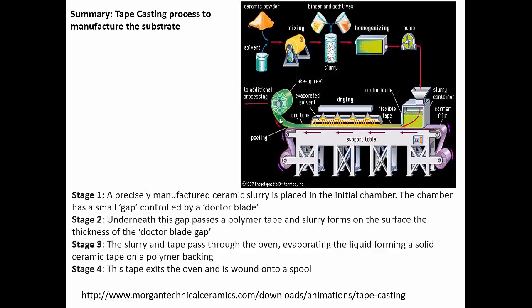So this is scalable, and it's a commonly used method in other ceramic technologies, in particular things like multi-layer ceramic capacitors based on barium titanate. These devices are mass produced using tape casting. So tape casting is a reel-to-reel scalable process for making thick films of ceramics. And by thick film we normally mean anywhere between a few microns up to say 100 microns.